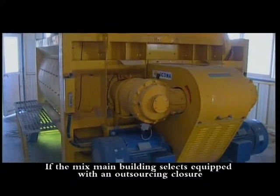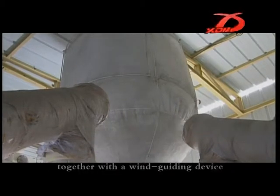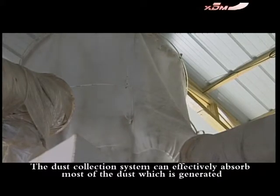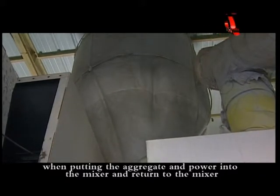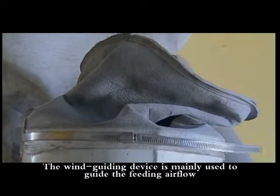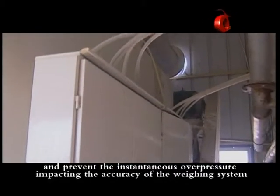If the mixing main building is equipped with an outsourcing closure, the interior will have a bag-type dust collection system, together with a wind guiding device. The dust collection system can effectively absorb most of the dust which is generated when putting the aggregate and powder into the mixer and return it to the mixer, reducing dust pollution of the environment. The wind guiding device is mainly used to guide the feeding airflow to outside the main building in a short time and prevent the instantaneous overpressure impacting the accuracy of the weighing system.